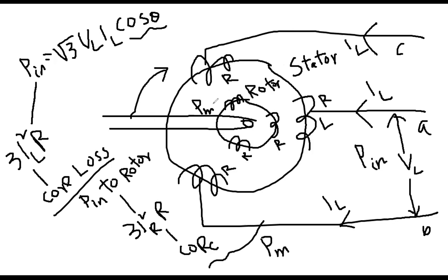Once the motor has started rotating, there is friction loss, windage loss, because this shaft is confronting the wind. So friction loss, bearing loss, and then as I told you, because of the working principle, there will be a magnetic field here, and another magnetic field here. There will be interaction. During interaction, there could be some non-linearity, some non-uniformity in the magnetic field. There could be some harmonics also. So we have to subtract what we call the hysteresis loss.